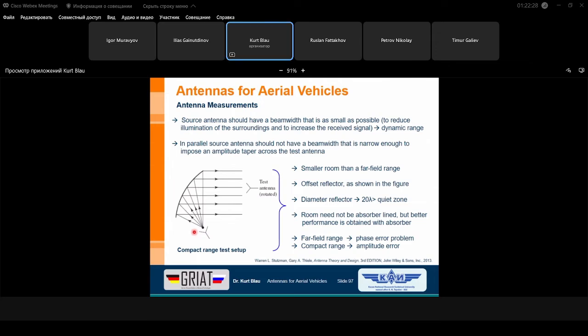If you look there, if we add the distances, or the lengths of these vectors, it seems to be the same. But across this plane you have very small phase errors, because you can compensate this with the shape of this reflector.